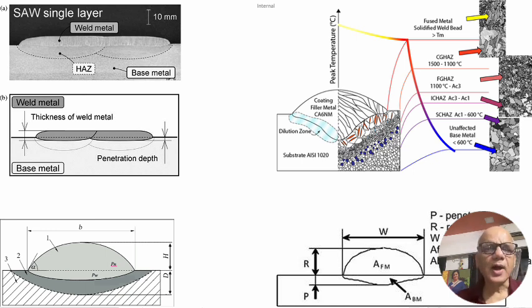So you have basic welding deposition here, that is the primary surface, but there is a diluted layer, and beyond the diluted layer, depending upon the temperature the parent metal or the base metal is going to see, you are going to get different structures, and some of them are hard. So those are the ones which are really worrisome in our heat affected zone, and others can have slight stress relieving, so a lower strength also sometimes you get.